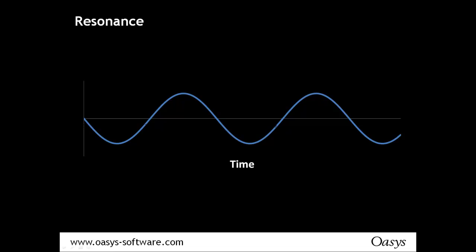Now, there are two types of vibration that you experience from footfall: resonance and transient response. Resonance is when the vibrations build up over time. If you look at this floor level, it vibrates over time at a particular frequency. Somebody comes along, and if their footsteps land on the floor in time with the vibrations, those footsteps will gradually increase the amplitude of the vibration, and you get resonance. You get a build up from that person walking around.